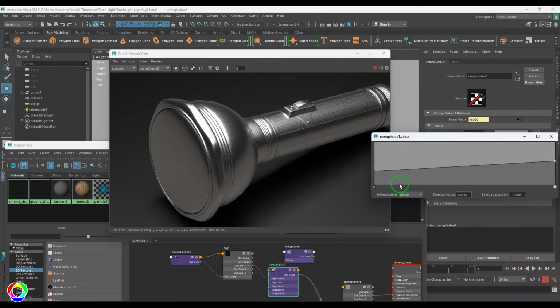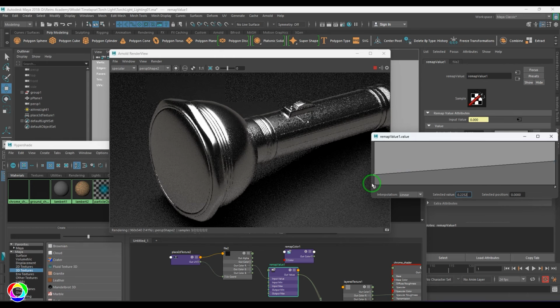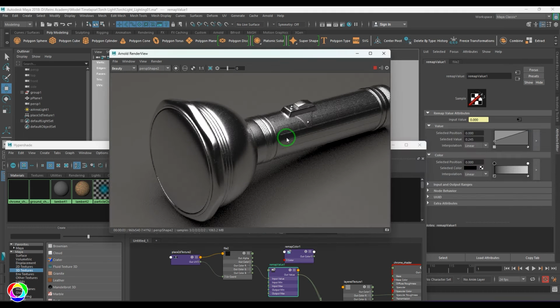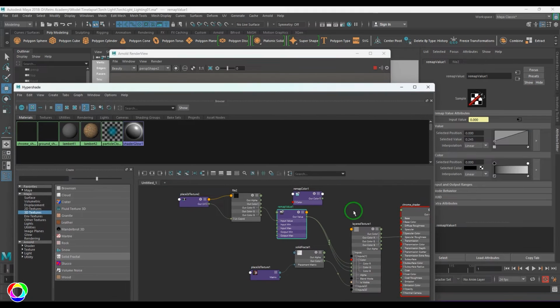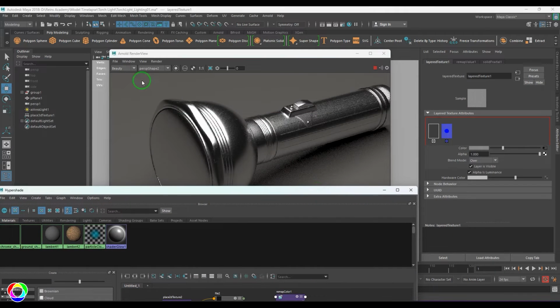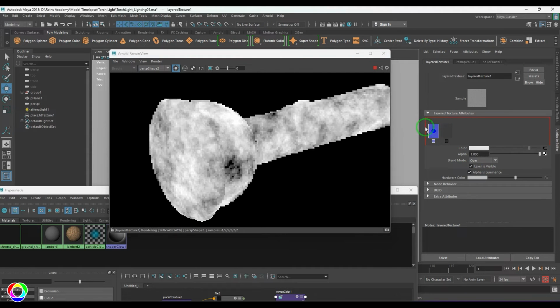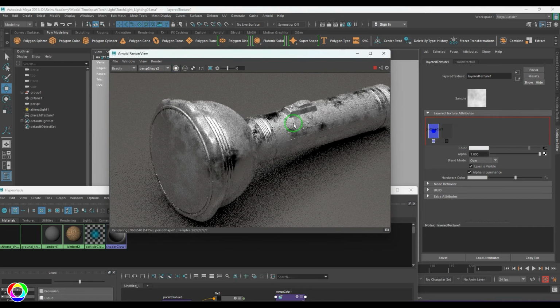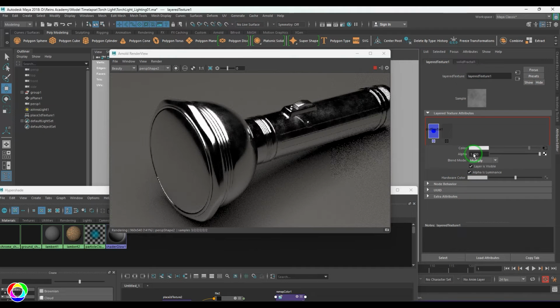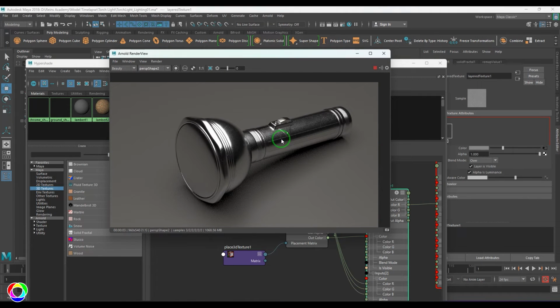Okay, I'm just making that part more rough and this part more glossy. Then it may start showing up the result. Yeah, now it's showing up. So the scratches, and let me just go to the layered texture, enable the isolate button on, and then we have this solid fractal sitting. I'll be moving on the top here, so that makes this texture look more this way. So I'm going to multiply this. Okay, and I'm going to reduce the opacity of this texture, and that gives a slight variation in the specularity overall. So this looks good.